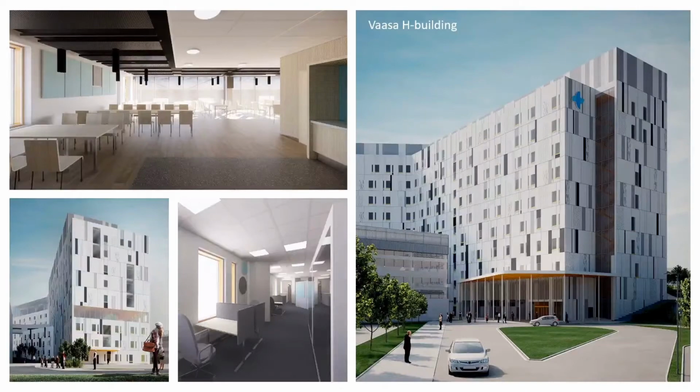And I guess what I mentioned during the presentation and during the demo is that you could actually move data which already existed. So I'm assuming those 5 projects, especially maybe that Fast IH building, maybe it was already started before BIM 360 design and then moved on to BIM 360 design, or maybe one of the latter ones. Yeah, actually all of them were old projects or already started. So it's already started, and that's what I mentioned in the presentation as well. It's quite easy to take that central file, detach it, and just say, okay, we're going to push this into the cloud now. Everyone gets a local file, and they're good to go actually.